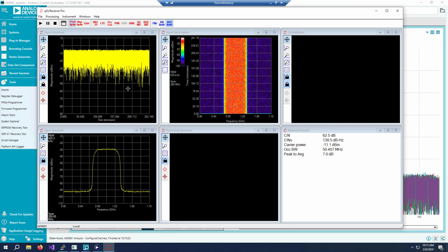This is the spectrum of that IQ data. This is a spectrogram, so joint time frequency. Frequency is horizontal, time is vertical. I like this plot because if our circular buffer has a glitch in the waveform, you'll see some spectral splatter here, horizontal lines in that. And so we don't see any of that. So we're doing good in that regard.